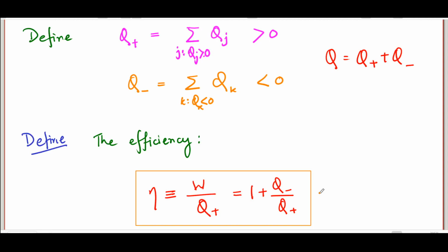So when we said that the second law actually says you can't even break even, you can see that in this formula. Eta, the amount of work you get per unit amount of heat supplied, cannot even get to the break-even point. W can never be equal to Q plus, it will always be less. And less by an amount depending on the temperatures of the reservoirs being used. We will see all that when we come to discussing the second law in a later lecture.